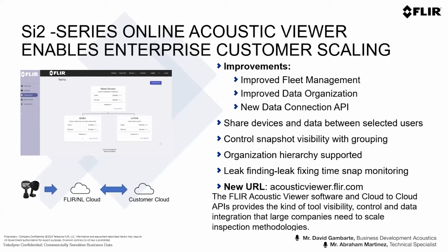And that's also coming to the Excel downloading report. So you can use that data, for example, to establish protocols where you say, okay, we need to fix the leaks that we find within 1 week or within 2 weeks, or any leak over a certain size, for example, 20 liters per minute. We want to fix it immediately, the next day or after 2 days, and then any leak below that, maybe you have more flexibility. It depends on your own protocols and policies, but you can use this as a very powerful tool to monitor the use of the cameras and monitor as well the cost saving.